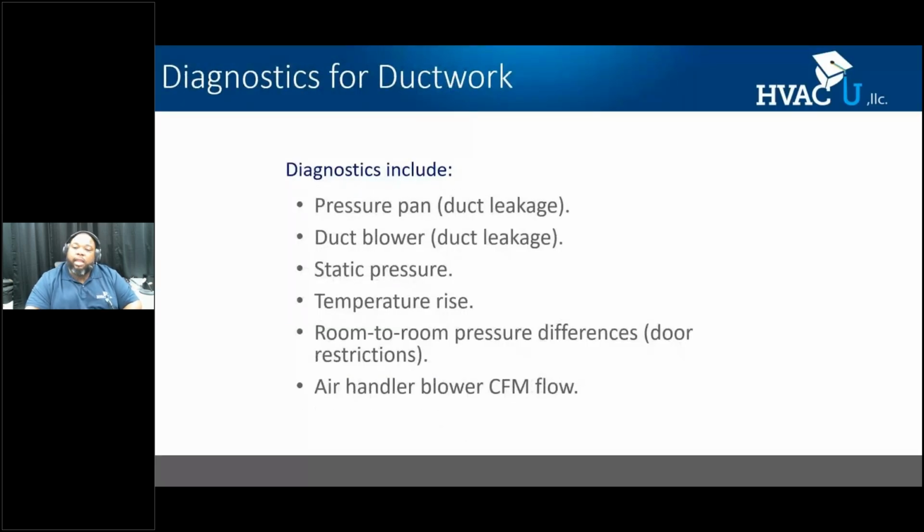All right, here are some diagnostics that you want to keep handy, and these measurements will help you uncover just about any kind of ductwork issue. We'll talk about the pressure pan, the duct blower or duct leakage tester, static pressure, temperature rise, room-to-room pressure, and then actually measuring air handler flow.